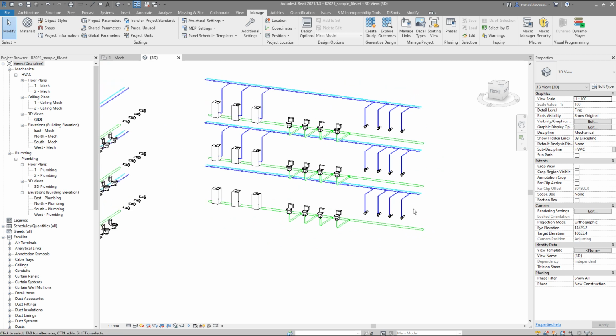We cannot rely on Revit IDs because I don't know how and why, but Autodesk did choose some methodology to assign those IDs, and basically nobody knows how to explain that. So if you are trying to create anything inside Dynamo to connect something, separate something, you should be extra careful when you need to rely on Revit IDs.